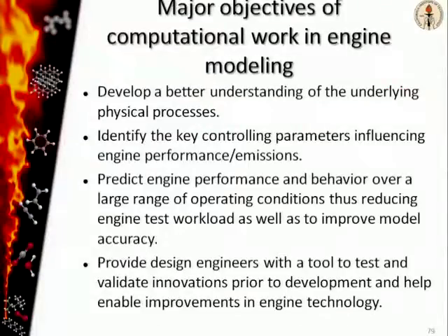Now, the major objectives of doing this kind of computational work in engine modeling are, one, to develop a better understanding of the underlying physical process; to identify the key controlling parameters that influence engine performance and emissions; to be able to predict engine performance using these models, so that you can reduce the workload for the test operator, who is basically getting the same data by running very expensive tests on these engines. You also want to provide data to design engineers who can validate innovations in engines prior to their development, and come up with improvements for improved performance from the engine.